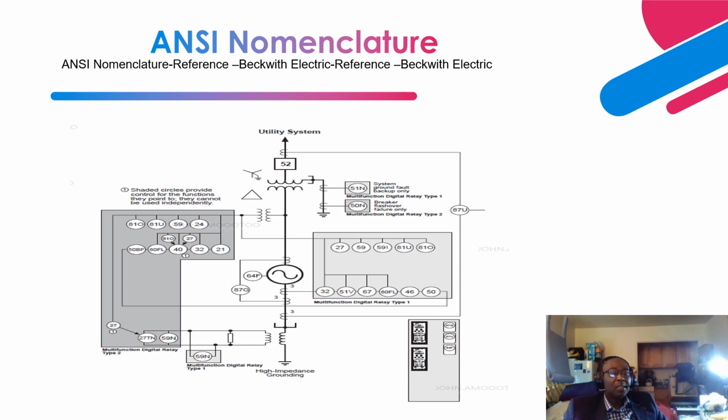This is the generator step-up transformer. This is what steps the voltage from the terminal voltage of the generator to a higher voltage. So let's say you have a typical generator that has an output voltage of 30.8 kV, and you step it up to 230 kV or 345 kV. This is implemented by the generator step-up transformer. It steps the voltage up from 30.8 kV to 230 kV or 345 kV based on the desired voltage that you need on the transmission end.